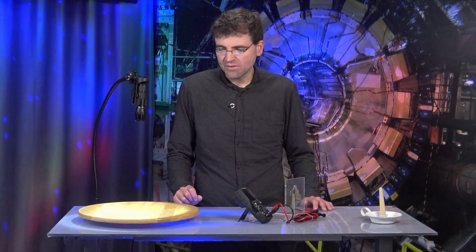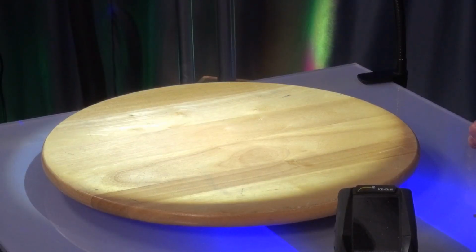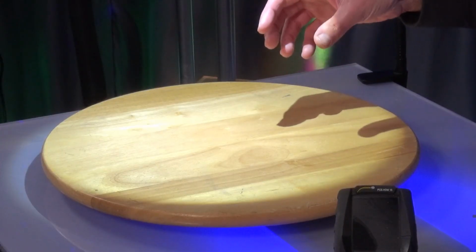And this is where the next unit comes in, which we can use to describe the light. If we illuminate a square meter of surface from a distance of 1 meter with 1 candela, then we have 1 lux at every point on the surface. But to keep things simple, there is another unit, namely the lumen. And the lumen is independent of the area that is illuminated, but it is about the luminous flux, about the light that comes from the light source.